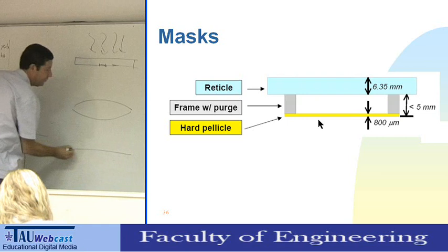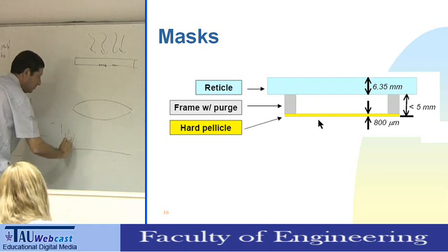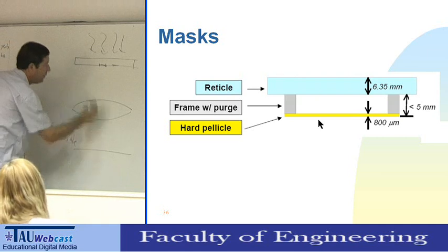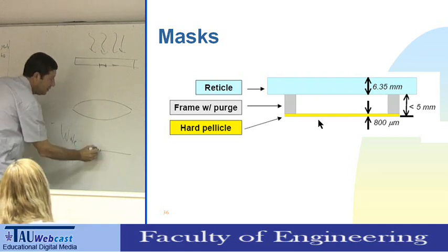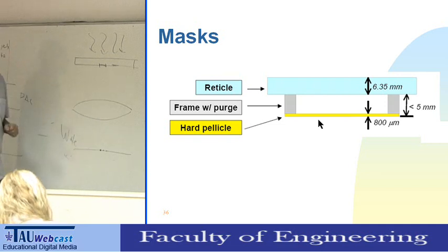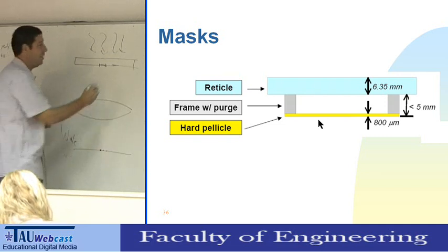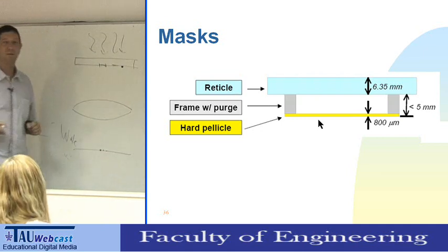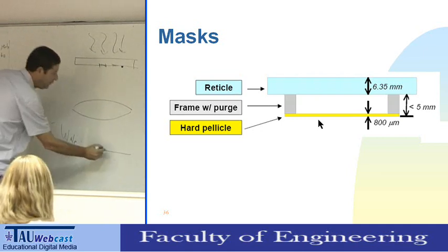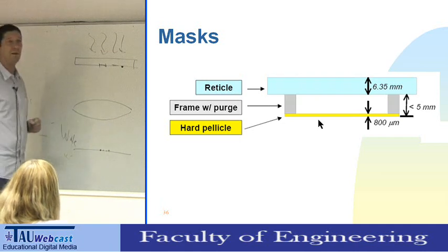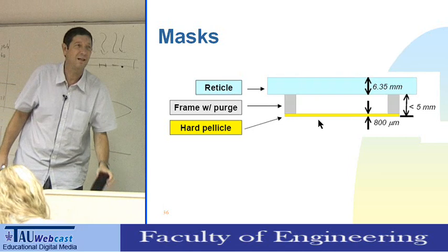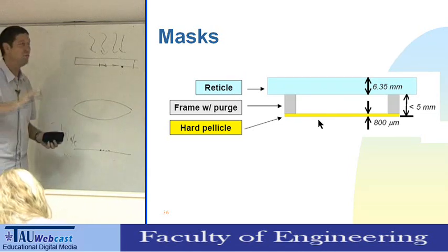And this is my wafer. I get the image of the structure, and if I'm in focus, I get the same feature here reduced, and everything is fine. Let's say now, for some reason, I have here a defect, some dust particle. On every feature, I will get this dust particle. So it will ruin my day, basically. So the yield will go to 0.